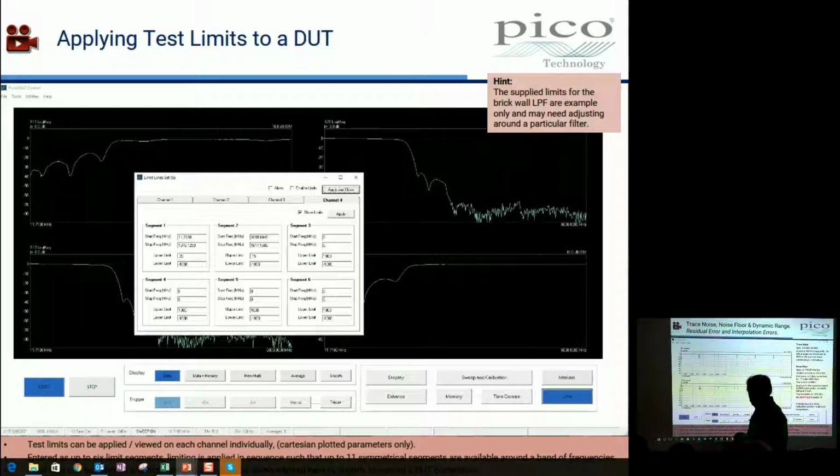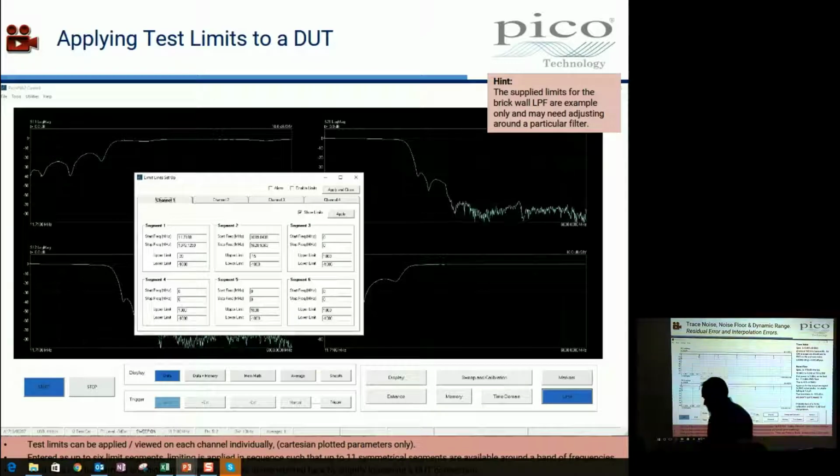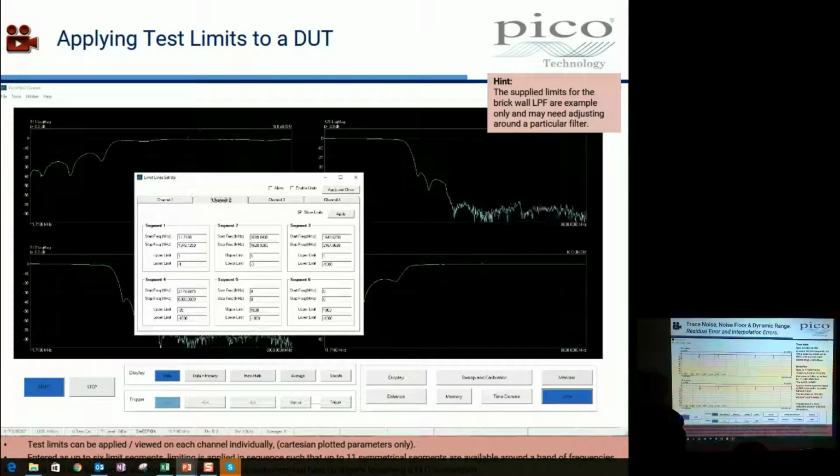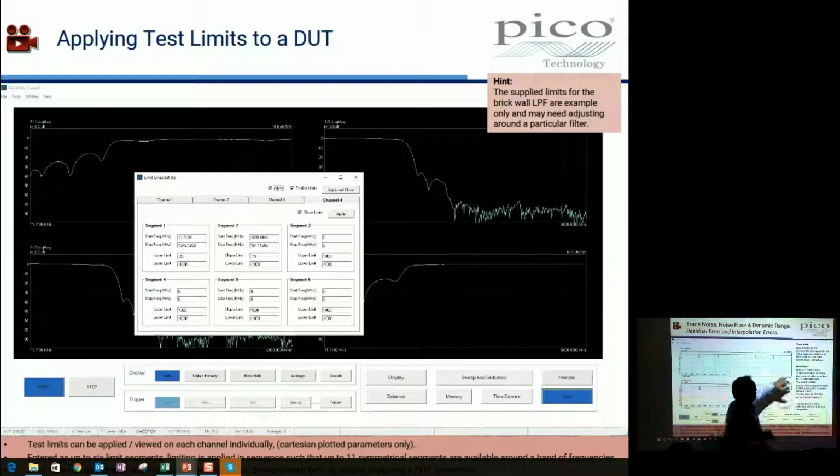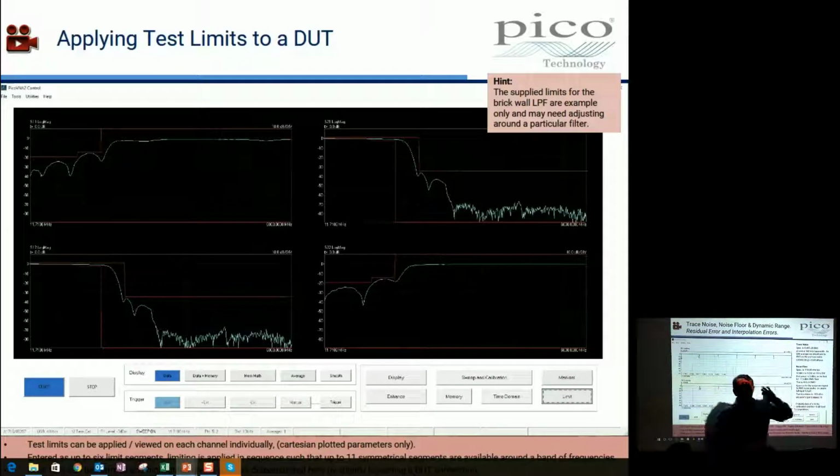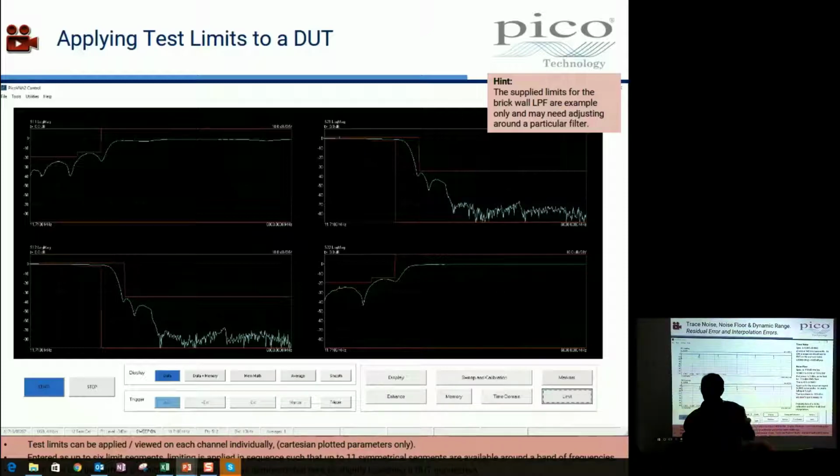So when we see trace noise, the peaks are going to be about 3 times bigger than the spec. Okay, so do be careful. You're not going to see necessarily this very low level when you look at it peak wise, you're going to see more.